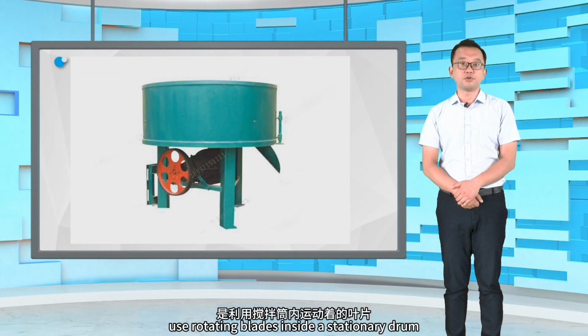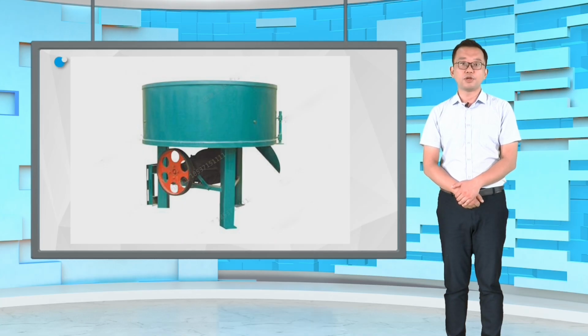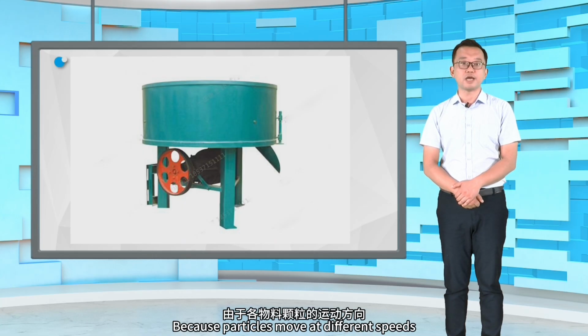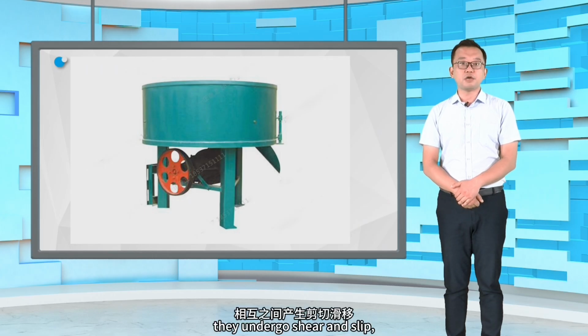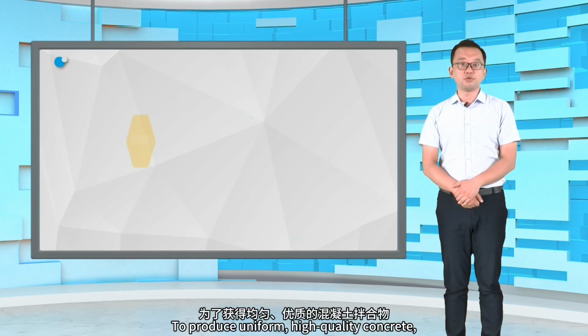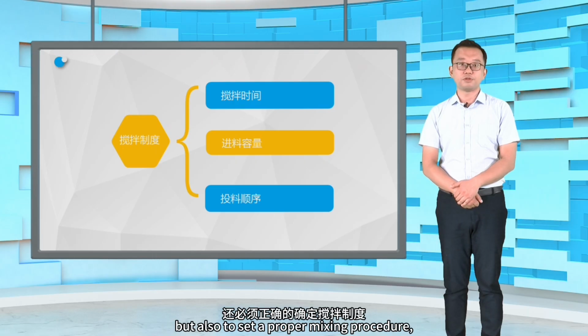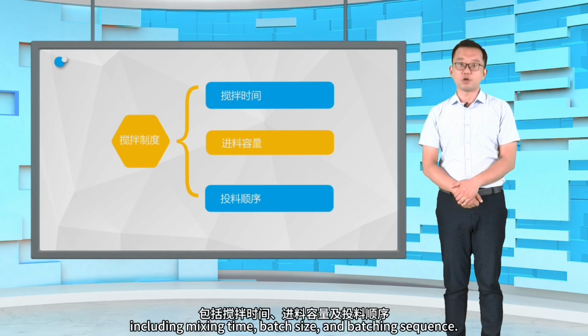Forced-action mixers use rotating blades inside a stationary drum to push and force the materials to move in all directions. Because particles move at different speeds and along different paths, they undergo shear and slip, intermixing and dispersing, which achieves a uniform mix in a short time. To produce uniform, high-quality concrete, it's important not only to select an appropriate mixer type, but also to set a proper mixing procedure, including mixing time, batch size, and batching sequence.